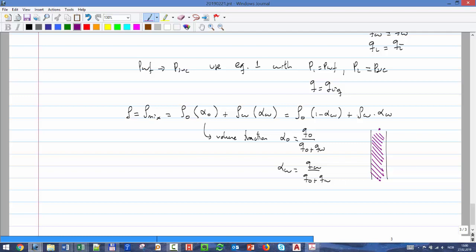So this definition is honoring that. It's honoring that if I have now two fluids on my tubing, it's honoring basically the hydrostatic pressure, even though they are not segregated, okay, they are mixed, but the effective density is using this expression, okay.